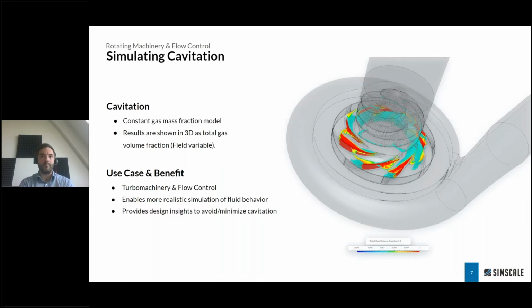Here we're looking at a rocket pump, also water turbines, these kinds of things. And obviously, not just is a cavitation model oftentimes important, or at least considering not ignoring cavitation, oftentimes it's important for accuracy, true, that you're getting the right performance predictions, but also the cavitation itself is oftentimes of high interest because obviously one wants to reduce the risk or at least limit the regions where cavitation can occur.